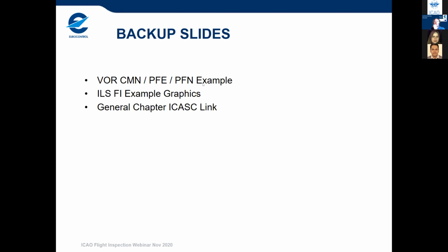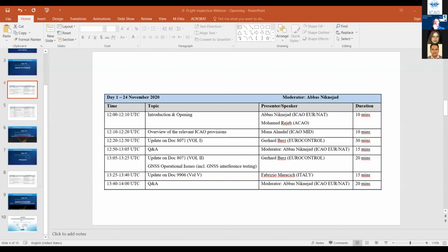We have a total of 52 NDBs in the whole Middle East region. At a global level, I would like to recall ICAO Assembly Resolution, I think 37-11, about implementing PBN. And we know that NDBs serve no role in PBN implementation, except as a means for position cross-checking and general situation awareness. And this minor role should not lead to the requirement to retain NDB facilities.